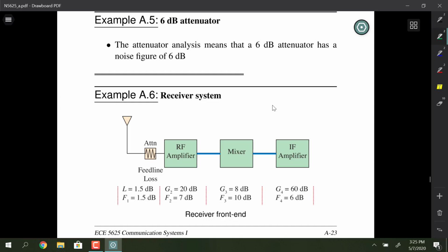You send the DC down the cable, right, and it comes up through an inductor, and the inductor is like a choke, right, and it blocks the RF from there. But then you just decouple it with the capacitor. Yeah, exactly. Okay. Some of you are interested in that.